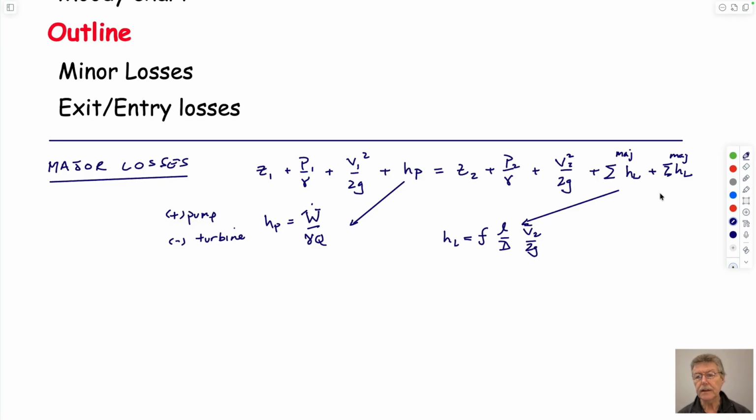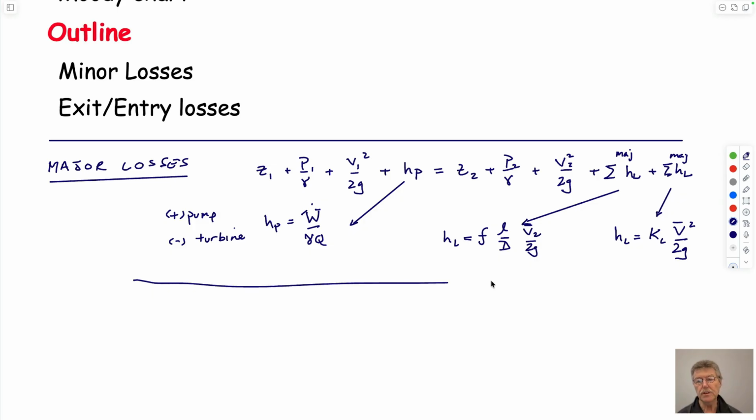And so, we didn't make the point here, but we said that head losses for fittings, going around bends and going through faucets, for instance, would be, as we've done in one of our examples, a loss coefficient times V squared over 2g. So very specifically, this is V bar, the average velocity within the pipe or the fitting. And so we have to at least be aware of that. From this, we develop Moody charts.